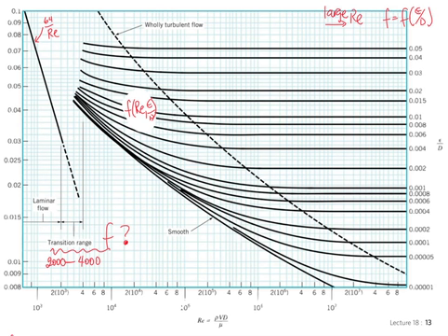The values are indeterminate. Now the other thing that we can note is that the value of the friction factor is not zero even for infinitely smooth pipes, because of course there's a no-slip boundary condition. So there's always friction. Even if the pipe is infinitely smooth, we believe in the no-slip boundary condition there. So that's what happens here. Even in this infinitely smooth case, F is not zero, which doesn't mean that there's no friction. There still is friction.